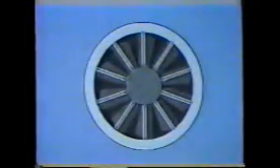When the guide vanes are open, large amounts of refrigerant vapor can flow into the impeller. But when the guide vanes move from the fully open position toward the closed position, the space between them decreases. This restricts flow and causes a pressure drop. This decreases the total amount of vapor that can flow in, but the compressor can continue to operate steadily with a reduced amount of vapor. In this way, the compressor's operation is controlled and its stability maintained in spite of a decrease in the load.